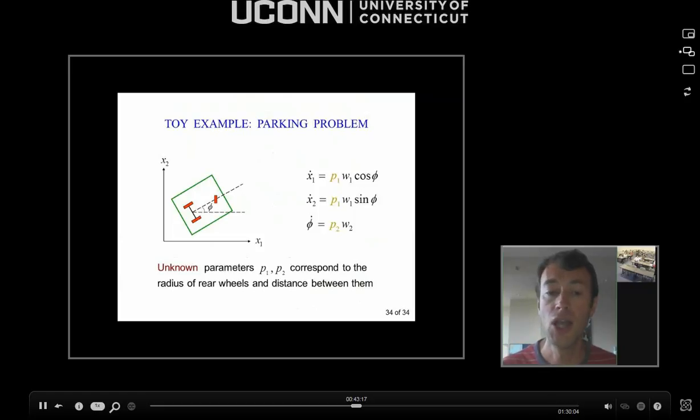supervisory control framework. So the thing that I usually emphasize in relation to such problems is that if you're going to have switching anyway at the higher level by means of the supervisor, this is quite suitable for working with quite general controller mechanisms at the lower level, for example, switching or some other type of time variation for low-level controllers. So in this sense, this framework is quite flexible in allowing more general candidate controllers than, for example, is typically used in traditional adaptive control.